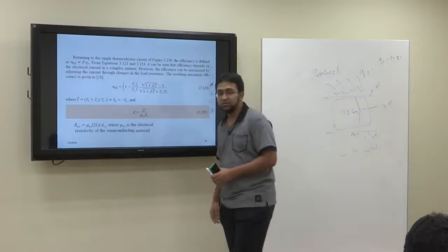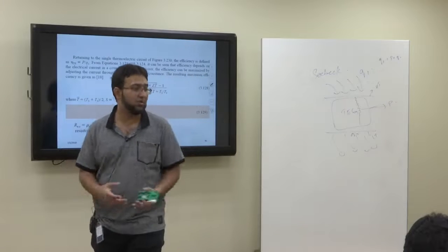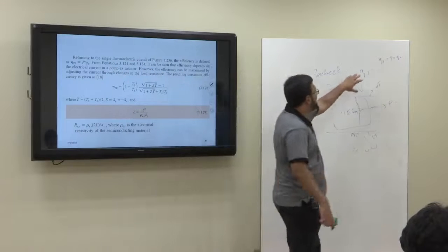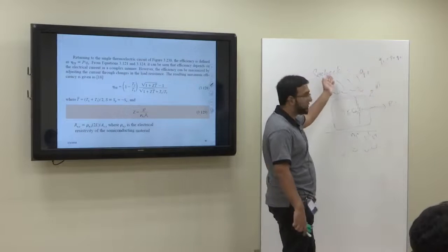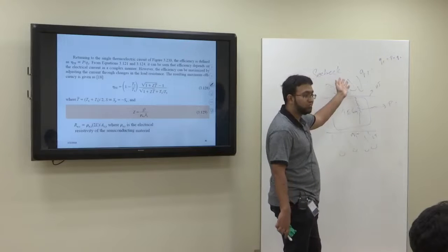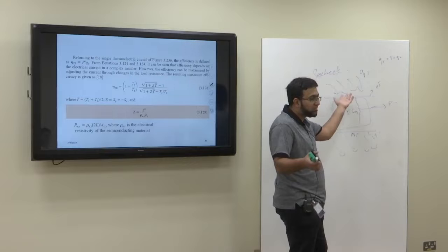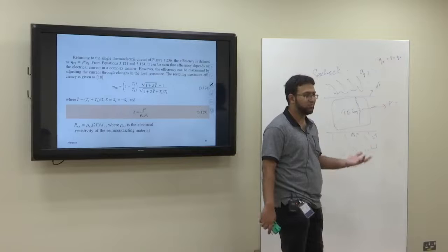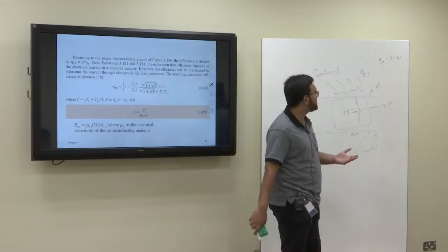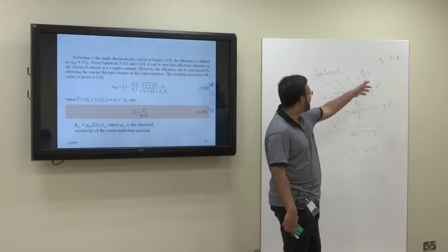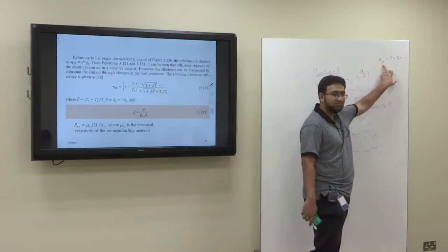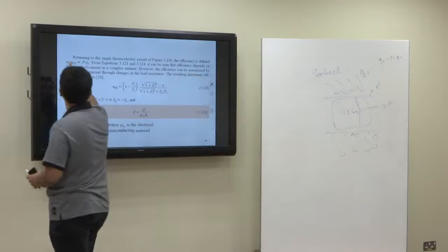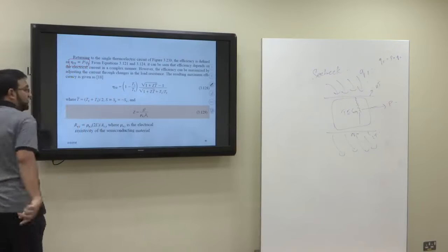The efficiency, how efficient your thermoelectric power generation is. Now in this case, if you see here, what is the input? Input is Q1. What is the output? Output is actually power. Q2 is there because if you do not produce Q2, then there will be no power. So basically efficiency is output over input. So efficiency will be what? P upon Q1, right? P is your output, Q1 is your input. So efficiency here is this, P upon Q1.